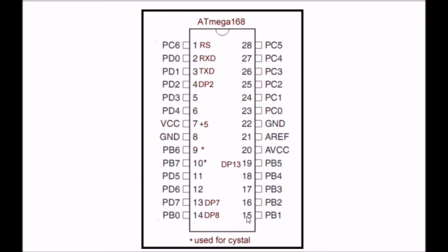So in the corresponding port B data direction register, I have to put a binary 1, which is pinMode(9, HIGH), or 1, or whatever you want to do. Keep this in mind. You don't have to remember this entirely. But whatever Arduino you are using, at least look up the device's spec sheet. Try to get familiar with what you're really dealing with.